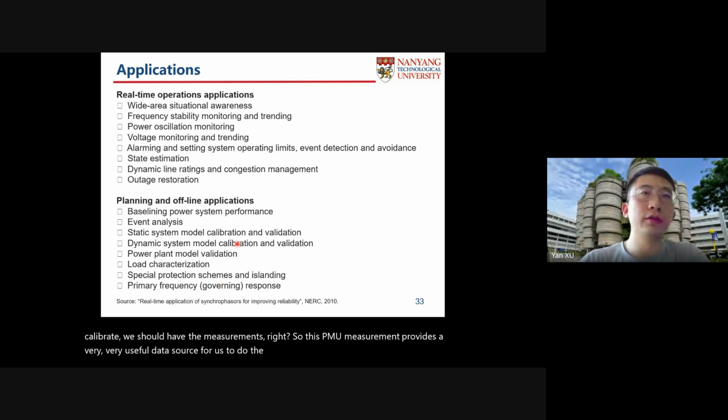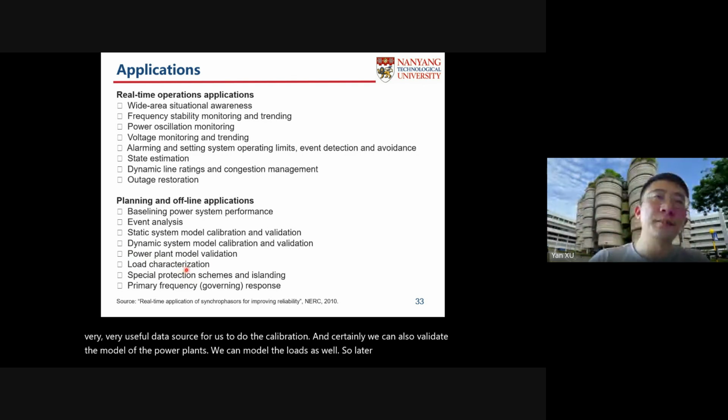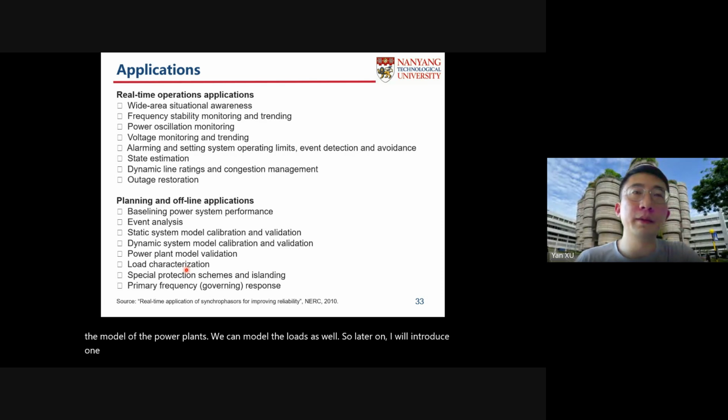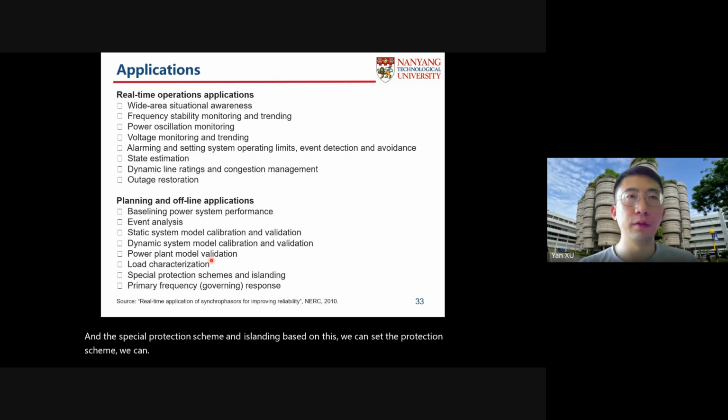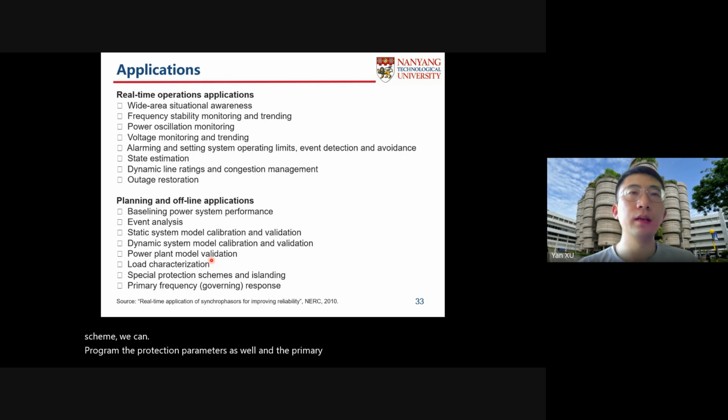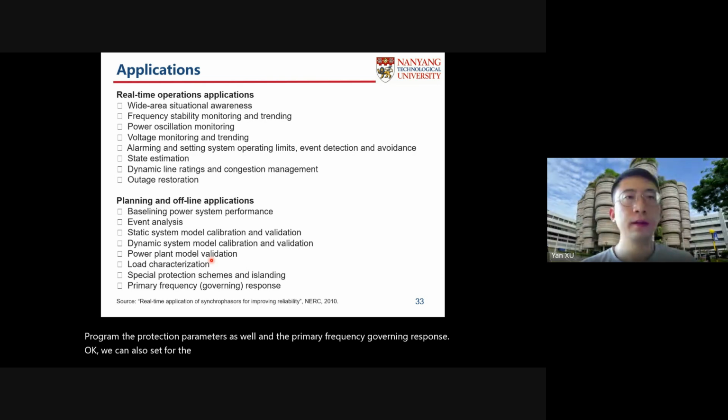And certainly we can also validate the model of the power plant. So we can model the loads as well. So later on, I will introduce one application for the load parameter estimation. And the special protection scheme and planning. Based on this, we can set the protection scheme. We can program the protection parameters as well. And the primary frequency governing response, we can also set for the frequency control system based on the PMU measurement data.